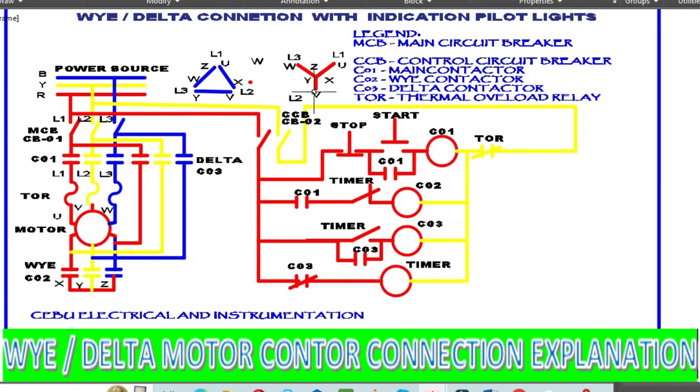As per this winding diagram, you already have line 1, line 2, and line 3, and then you have to short circuit the 3 wires, the endings of line 1, line 2, and line 3, as you can see on this Y contactor XYZ. Then you close XYZ, and your induction motor will run as a Y.